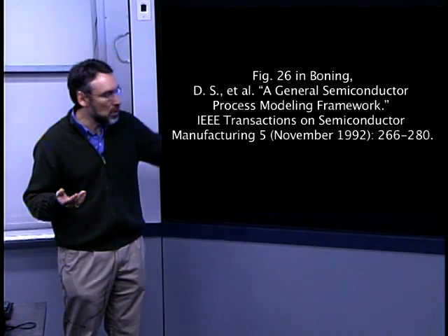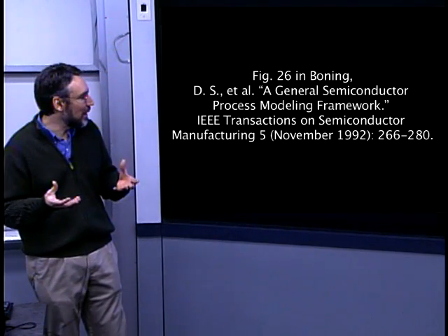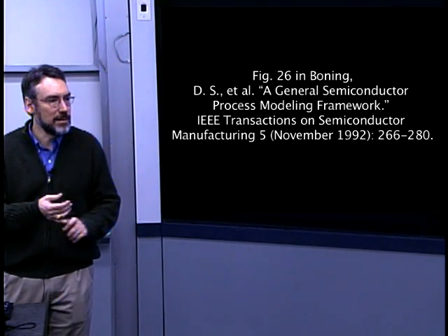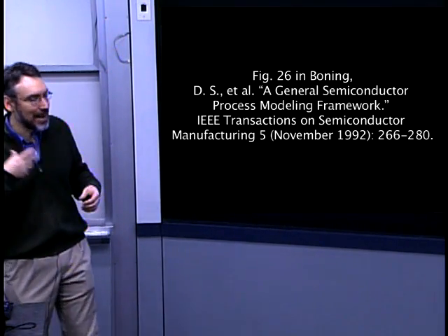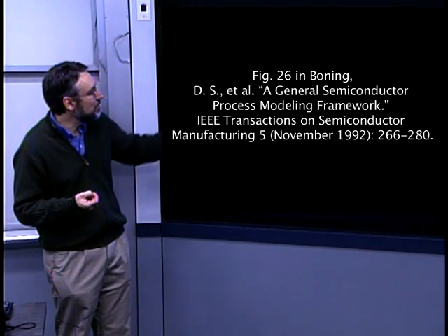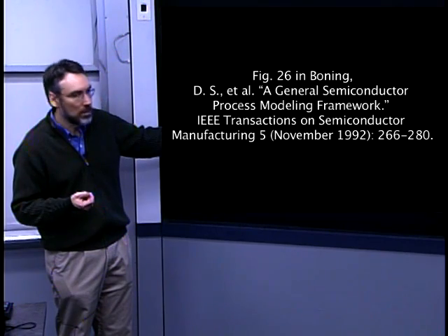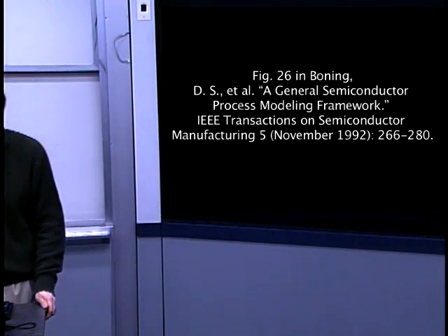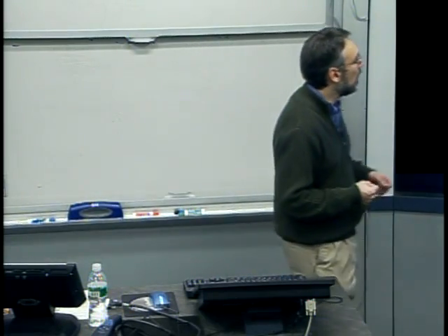We've got inputs in terms of the environment that we create around the wafer, that vacuum process, the chemical etchants, the gas ambient used in plasma etching, and then other control factors on the machine or the facility, things like thermal control in photolithography to ensure that there's no thermal expansion of the components.